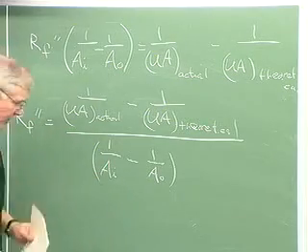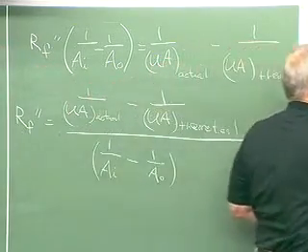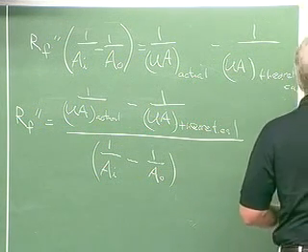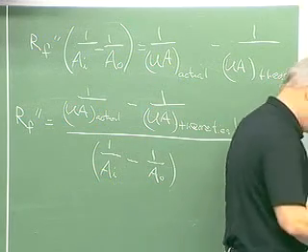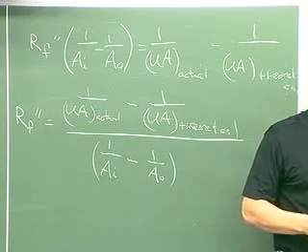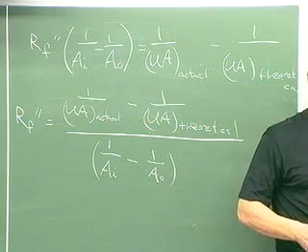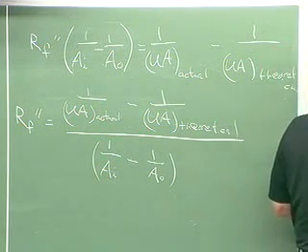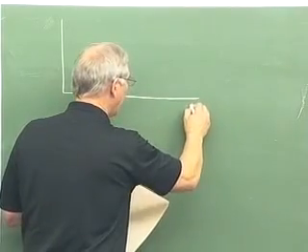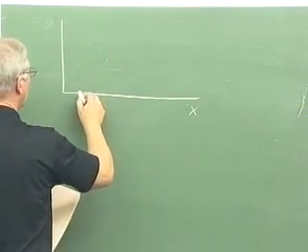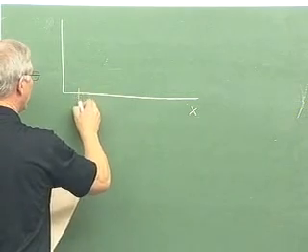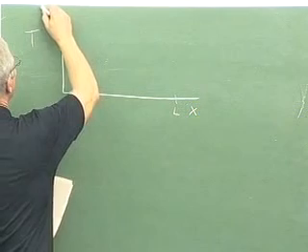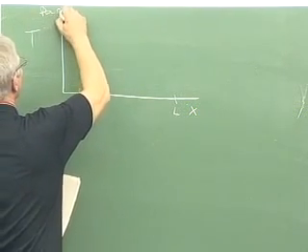Okay, the next step in the lab is to plot the hot fluid and cold fluid temperatures versus axial position in the heat exchanger for the different flow conditions. Okay, so if we put X down here, and we call this 0 and that L for the full length, and we plot temperature. For parallel flow, it'll look something like this.